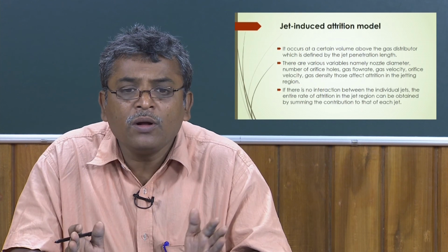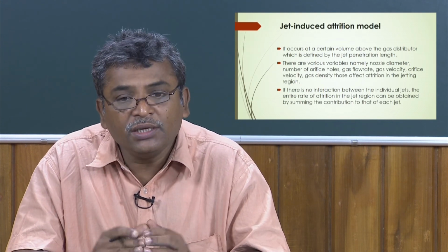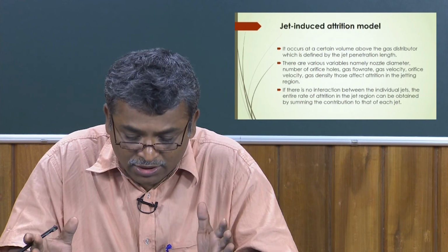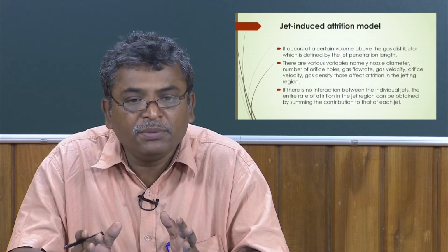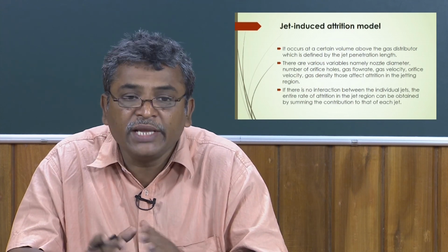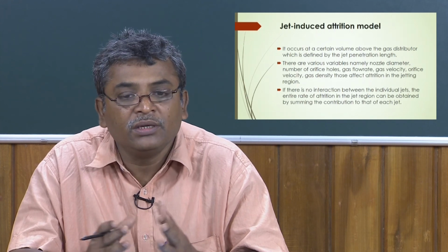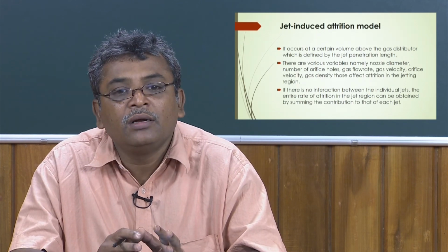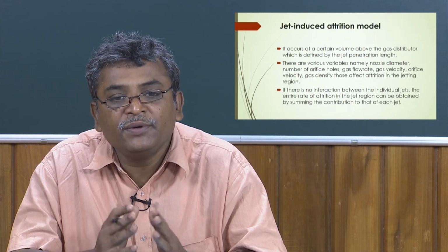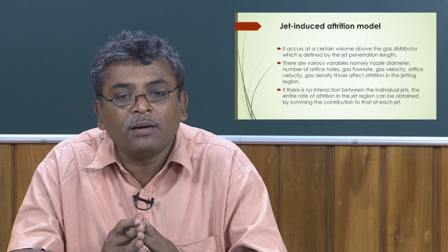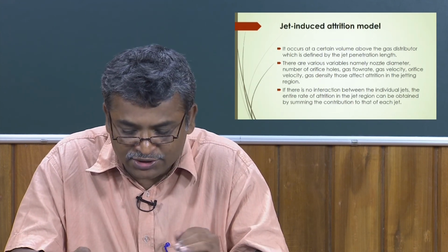That holds if there is actually no interaction among the jets. If there is interaction between the individual jets, then the attrition rate may change because of the collision rate and also the efficiency of the breakup of the particles in the distributor region.